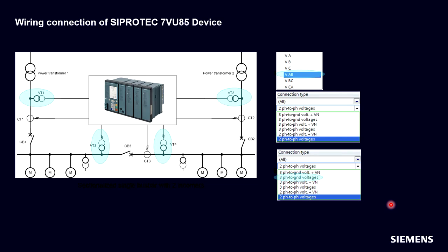And why do we use the three-phase voltage at first? Because the algorithm for the fast switching is based on a three-phase stable frequency measurement, and therefore we have this three-phase implementation, and also some additional supervision functions like phase sequence and other supervision functions for avoiding any mistakes.